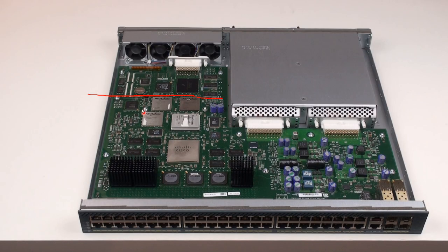From here downside, these are all the real ASICs which manage and process the packet switching, packet manipulation, and all the functions related to real packet switching. Between the CPU of this switch and the other components, it's normally a PCI Express connection within this PCB, which connects the CPU to the other components and also manages the main switching chipset.